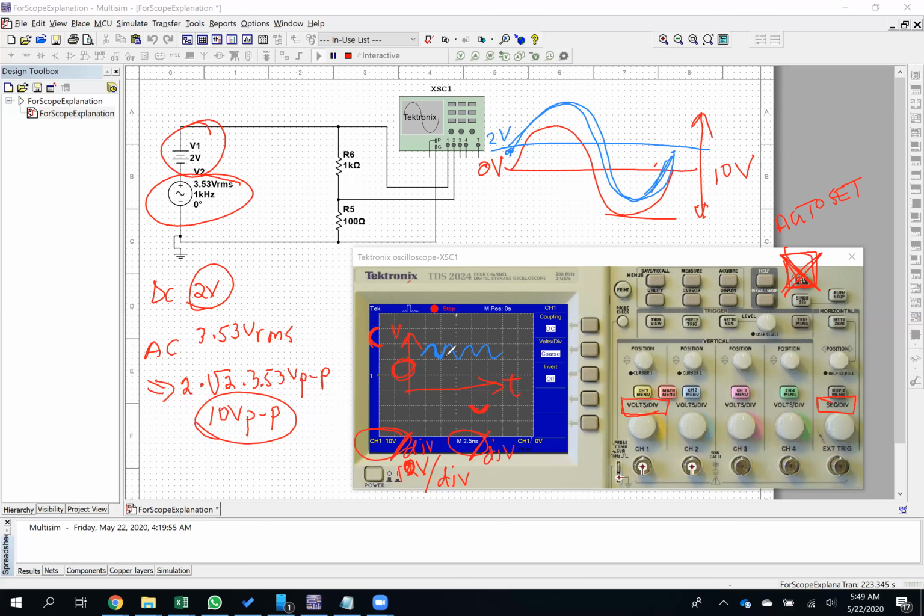It's really hard to visually take a good measurement from the scope with the waveform that small. So what I might do is change this setting to 2 volts per division, because then my waveform peak to peak would take up 5 divisions, and it's offset by 1 division, and top to bottom I have 8 divisions, so that's enough room to put my waveform quite large on the screen.